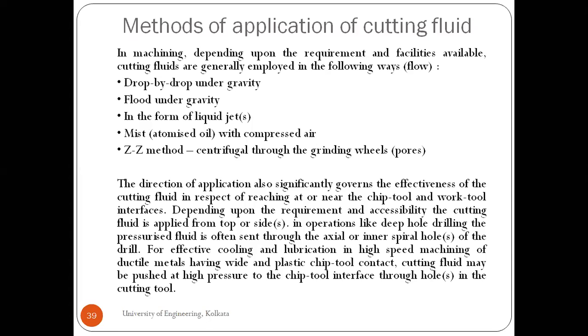Okay, so in that case we have to push the cutting fluid at a higher pressure, as Somnath was asking, in case we are unable to reach the proper zone. In that case what will happen, the proper zone will not be cooled, so we have to create some extra pressure into the chip tool interface, by which we can get the proper cooling.